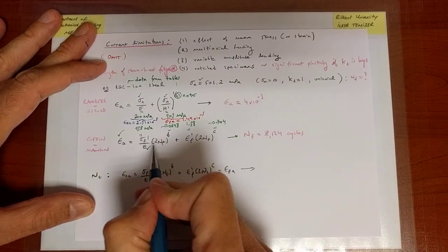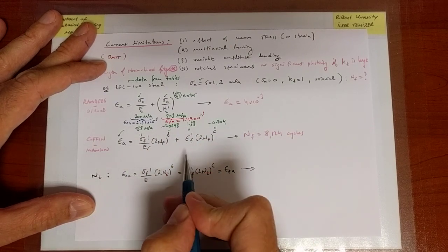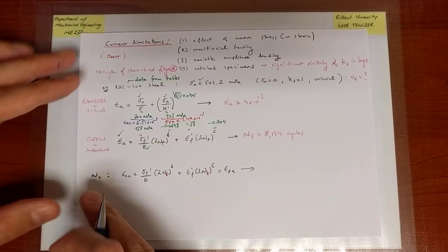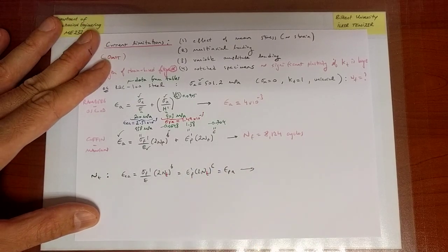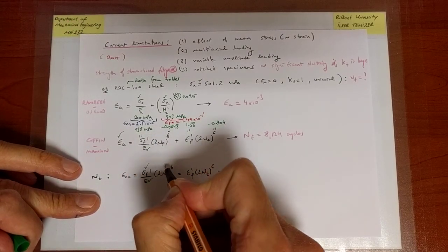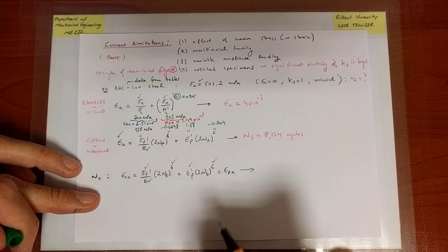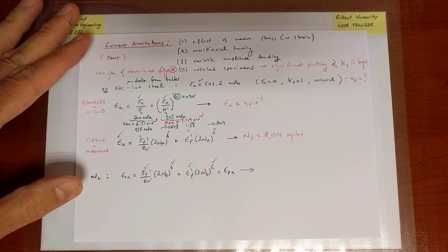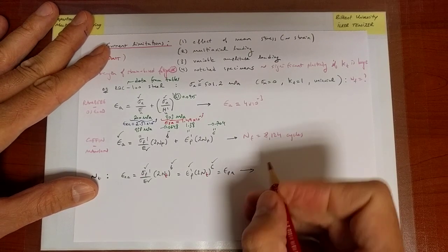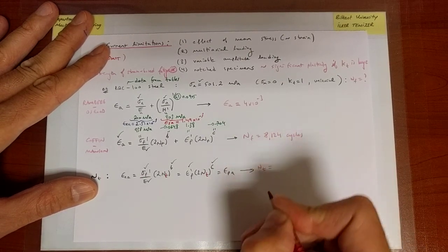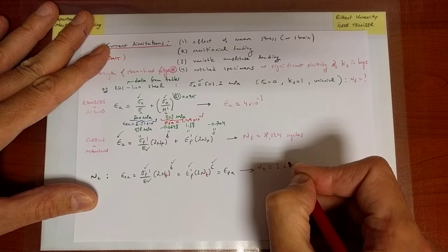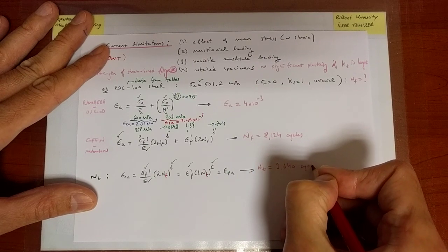As soon as I understand the individual contributions to the Coffin-Manson relation, I should be able to extract this information with an understanding of what the transition fatigue life stands for. Notice that we have everything we need to know. Sigma f prime, E, b, epsilon f prime and c are all known. So NT is the only thing that we need to extract from this equation, and therefore we can solve for it, and we find that NT is equal to, in this case, 3,640 cycles.